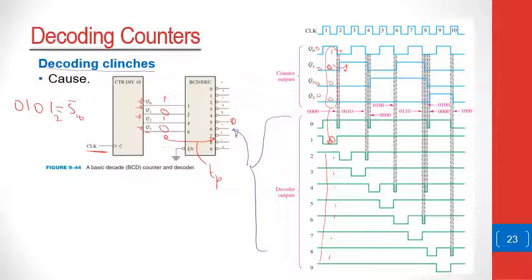So you will have a count which is intermediate here, and this count will be 0 0 0 0, and because of that, as this changes, this will deactivate the 1 and reactivate the 0 before it comes back and settles to the right value, which is the 2. Because at this stage it has to settle to 1, 0, 0, 0, which is a 2.